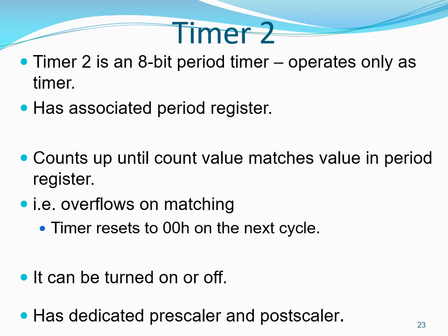In other words, the timer overflows when the value in the timer register matches the value in the period register. On overflow, the timer resets to 0. Timer 2 can be turned on or off. Timer 2 has a dedicated prescaler and a dedicated postscaler.